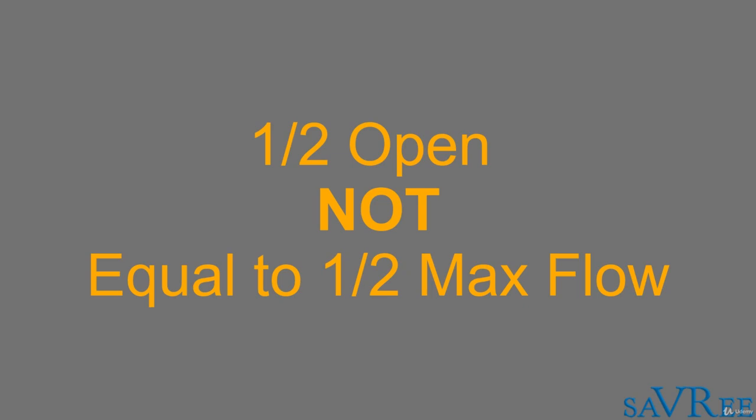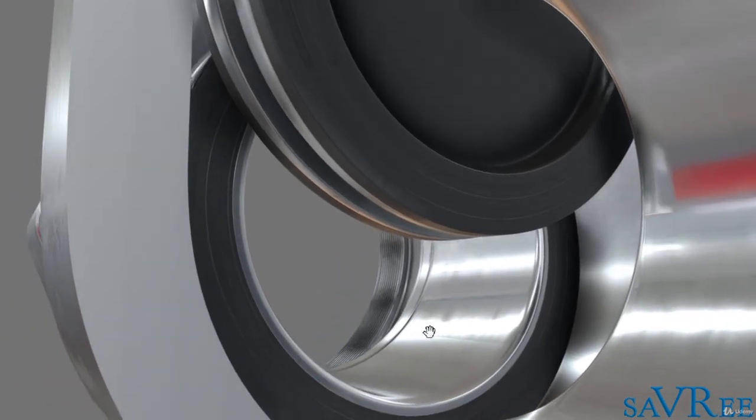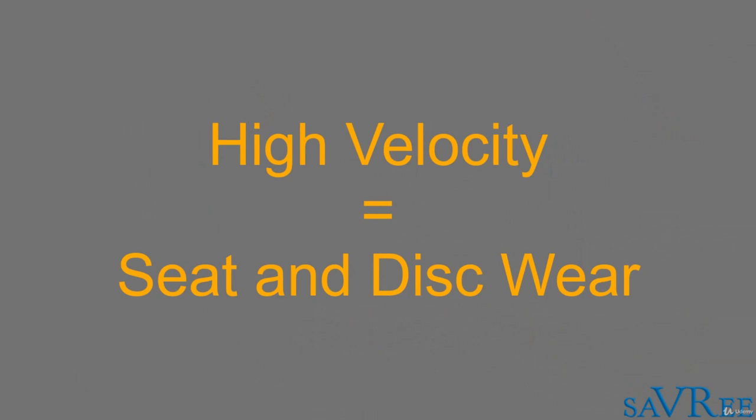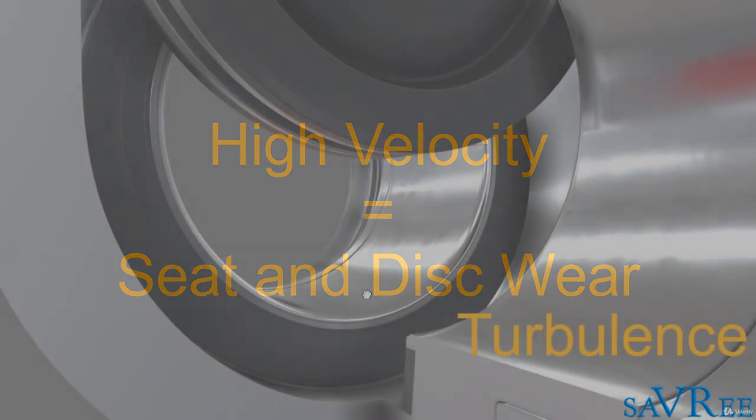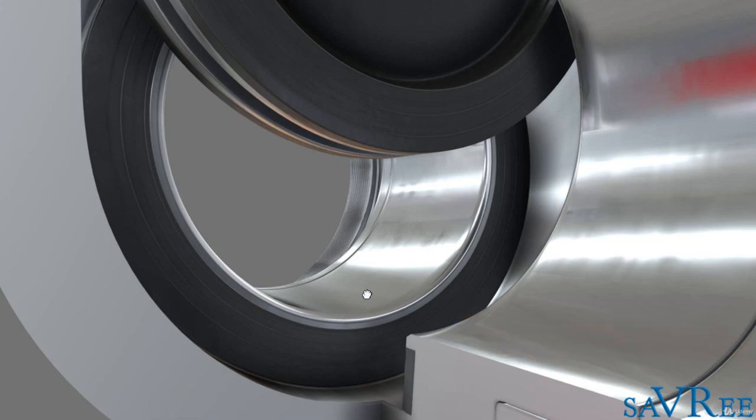This means that when you actually open the valve halfway, you're going to get a lot of flow between the disc and the body here, and this is going to be proportionally quite a large amount of flow with a high velocity. This high velocity often leads to seat and disc wear. The other problem, apart from the high velocity, is the turbulence. As the flow passes through this small gap between the disc and the body, there is a lot of turbulence, and this also creates a larger pressure drop, which again is what you don't want. This is resistance to flow. So gate valves are not very well suited to throttling. In fact, they should either be only fully open or fully closed.